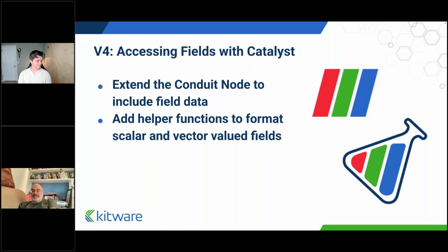One of the questions is: is Catalyst self-contained in the sense that it has all the necessary libraries to support both hardware and software rendering for in situ operations? Do you want me to answer that, or would you like to answer that? That comes from the ParaView implementation. ParaView has access to software and hardware rendering, depending on how it is configured for your particular system. If you have software rendering enabled with ParaView, then Catalyst will have access to that capability.